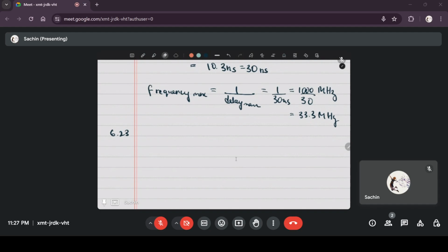Design a timing circuit that provides an output signal that stays on for exactly 12 clock cycles. A start signal sends the output to the state 1, and after 12 clock cycles the signal returns to the 0 state.